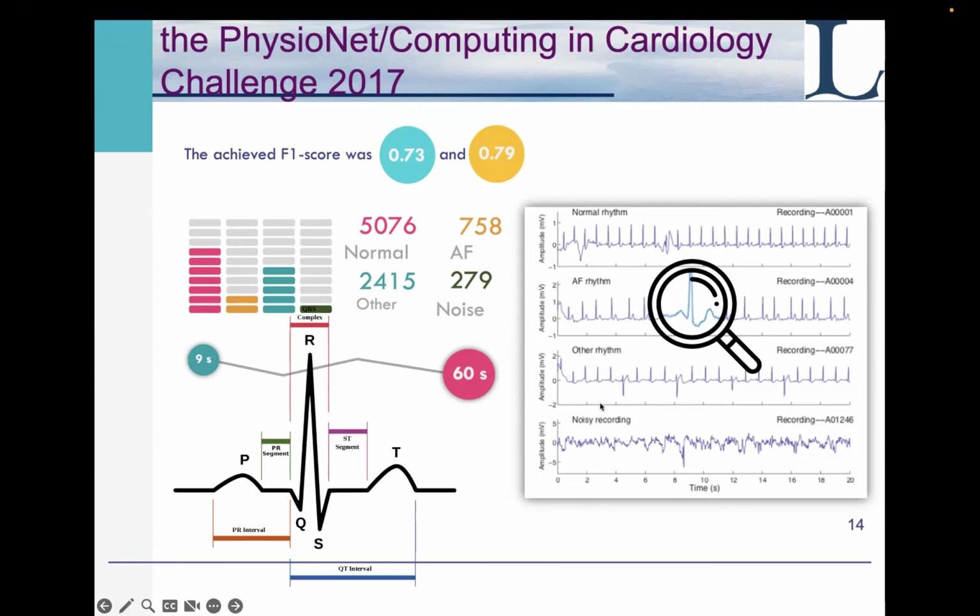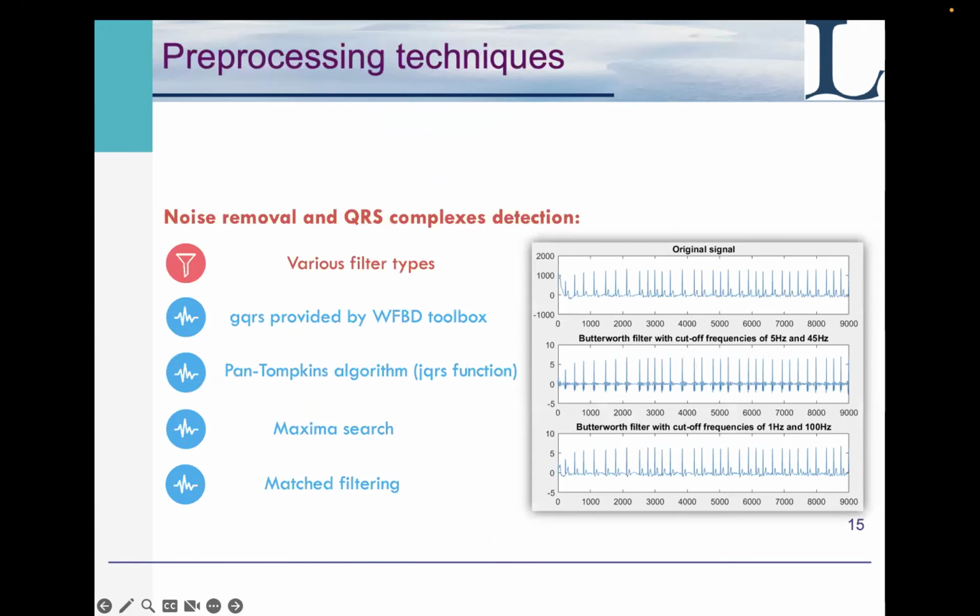And again, the steps before actually inputting anything to machine learning methods: one needs to do quite a lot of classical signal processing, like noise filtering and extraction of these PQRST sequences, or QRS complex, it is called.